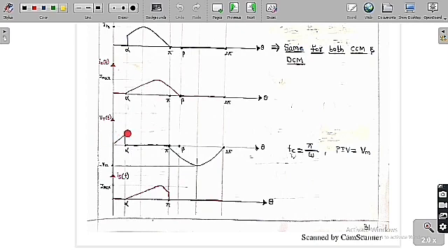So let me draw the voltage across the thyristor and the output current, say the source current. For the thyristor voltage, I already told you that from 0 to alpha we have not given any triggering, so it is a forward blocking mode. Whatever the source voltage is equals the voltage across the thyristor, so it is going to look like this. Whereas from alpha to pi, as the main thyristor conducts, its voltage drop is equal to 0.